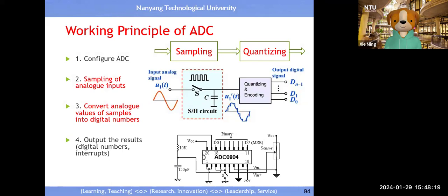Okay, so the video actually summarizes the key procedure. The first two, because the last one, the encoding, just packs the digital number, either binary number or hexadecimal format, is not important, right? So the important thing to remember is sampling and quantization. Because later when we look at the implementation of this principle, you will see similar terminology there, right? So you have a device which will do sampling, and you will have a device which will do quantization. So you must have 2 different devices to handle these 2 operations.